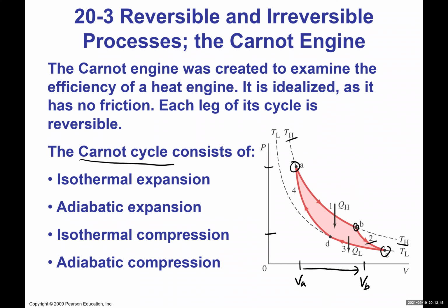For step 2, this adiabatic expansion, you can see this is basically Q2. You can say that Q for step 2 is 0 because there is no heat added or removed. But obviously, you can see that volume changes. So the system does work, right? Gases do work because there's an increase in volume. So gases do work, pressure decreases, but heat is not added. If the system does positive work because it's an expansion, the internal energy of the system will always decrease, because whenever the system does work, it does work by removing energy out of the system. It uses some of the system's energy to do work. So the internal energy of the system decreases and we have a lower temperature at point C.